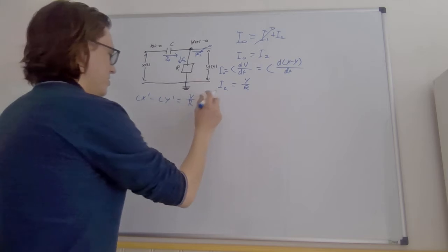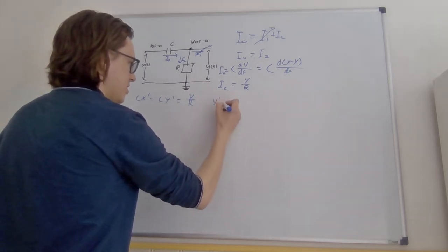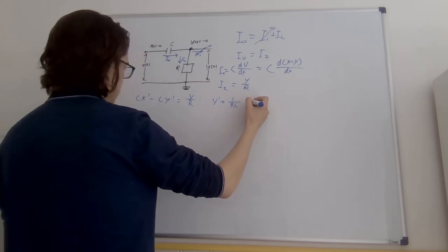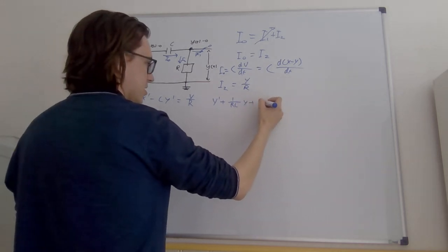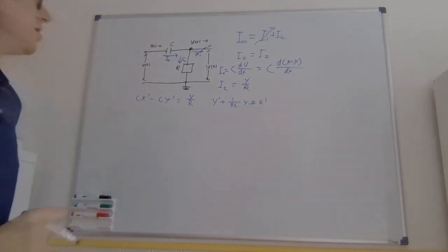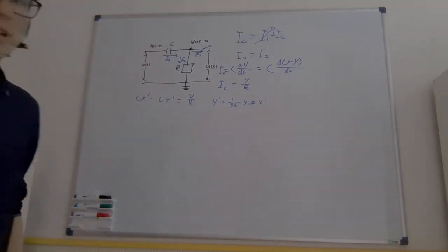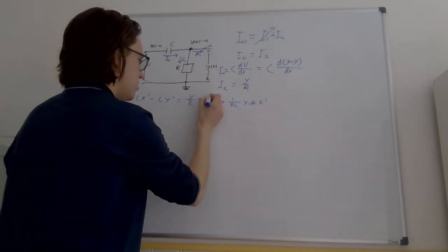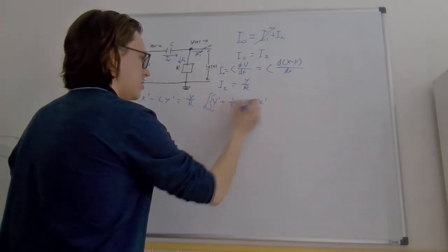We can massage this a bit, and then we get the formula y prime plus 1 over RC times y equals x prime. Next, we want to find the transfer function, so we take the Laplace transform of this expression.